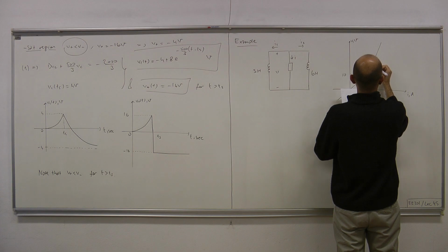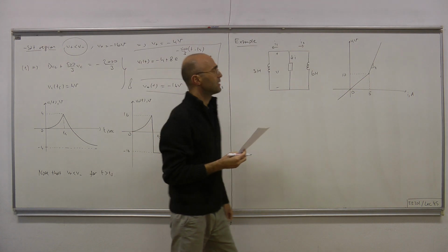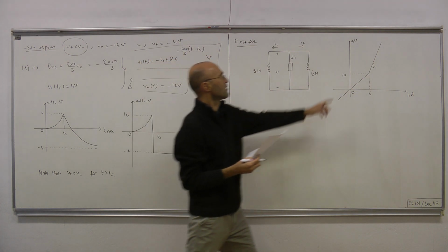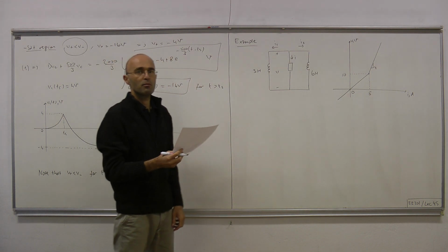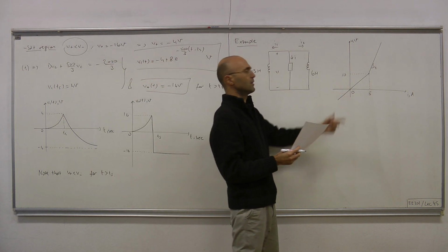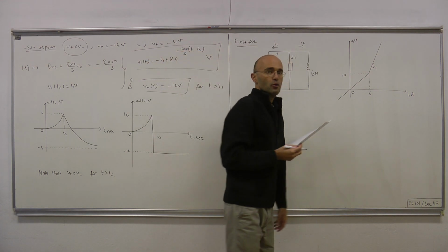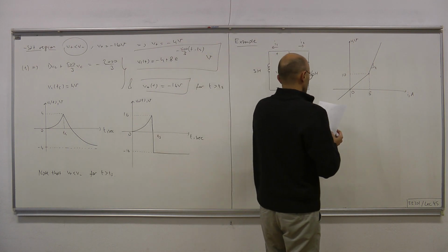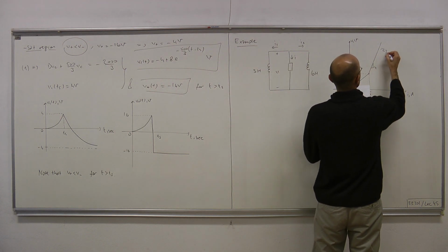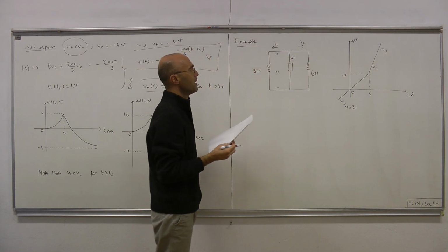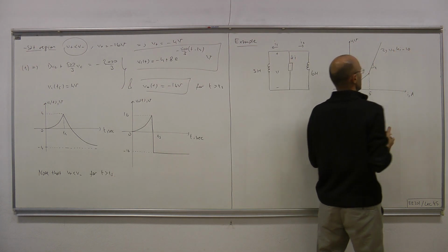Here the slope is given to be 4. And the slope here is clearly 2. This time voltage is the vertical axis, current is the horizontal axis. Therefore, slope gives us the resistance, or the unit of slope is ohms. Now here we have V equals 2I, and the curve can be described in the other region by V equals 4I minus 10.